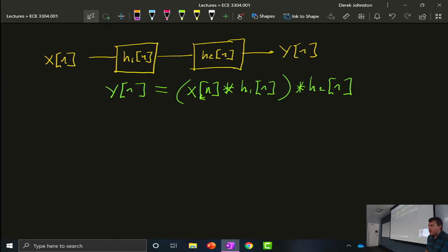And like before, is there a way to simplify this block diagram? People in Discord are getting answers. Oh, what do they say? Right. Convolve the h's first, and then convolve x with that. You're absolutely right. Convert to one block, which is the convolution of both impulse responses.